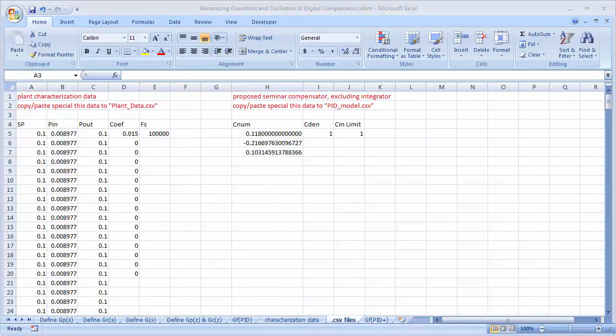Here is the generated data. COEF is the set of compensator coefficients used to collect the data set, and FS is the sampling frequency. In real physical systems, this data would be collected in the ISR. A typical control flow might be: take the ADC complete interrupt, read the ADC conversion, compute the error term, run the compensator, and output the next command to the plant. This dataset reflects this notion, that is, it takes non-zero finite time for the plant to respond to a command.